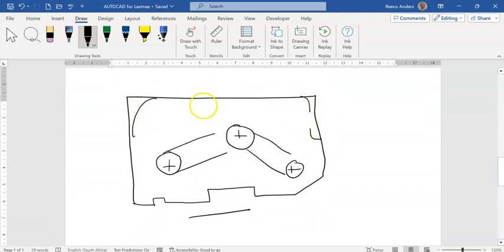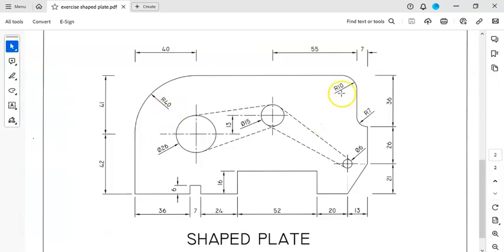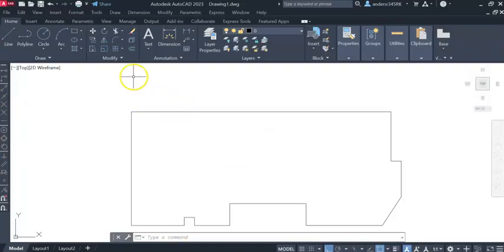and now I'm going to put in those 3 radii over there. 1 radius, many radii. Okay, right. If I go to my drawing, that's a 40, that's a 10, that's a 7. Right, and that's what I do. I go to fillet. Now fillet, chamfer and blended curves are sitting under there. So I'm going to go to fillet.